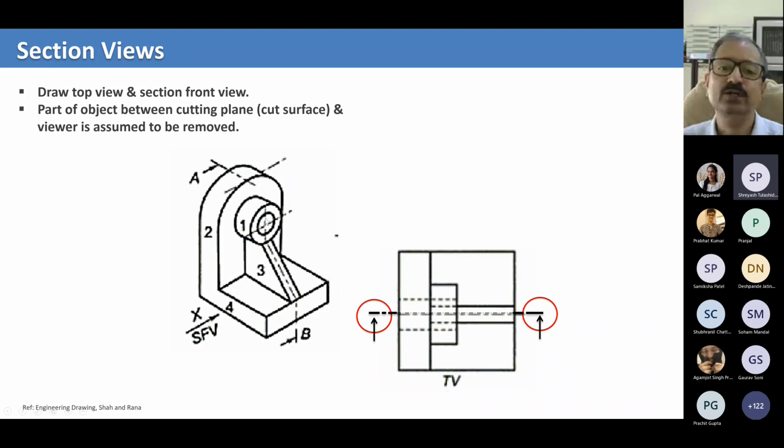And the dotted lines are showing you this hole which is going all the way through. If this dotted line is not there, you would never know that this hole is going all the way through. Correct? And then we have another line in the middle, which is the center line of the hole. This line, which is the center line of the hole, should be line dot line dot. And additionally, what you see is a cross-sectional plane which is outside the whole thing.